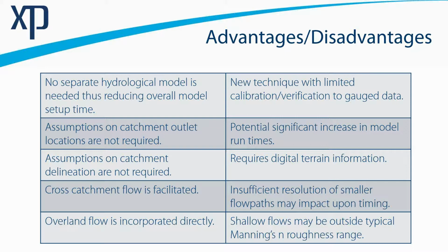What's important is that your main flow paths or your objectives of your study are being met. So if it's a very quick, broad-scale model, it's not necessarily that essential to be down to a very fine cell size. But if you're doing a high-resolution assessment of an urban area that has issues, and you need to get down to your buildings and your fences and your pits and your pipes, well then of course you want to be down to a fine cell size.